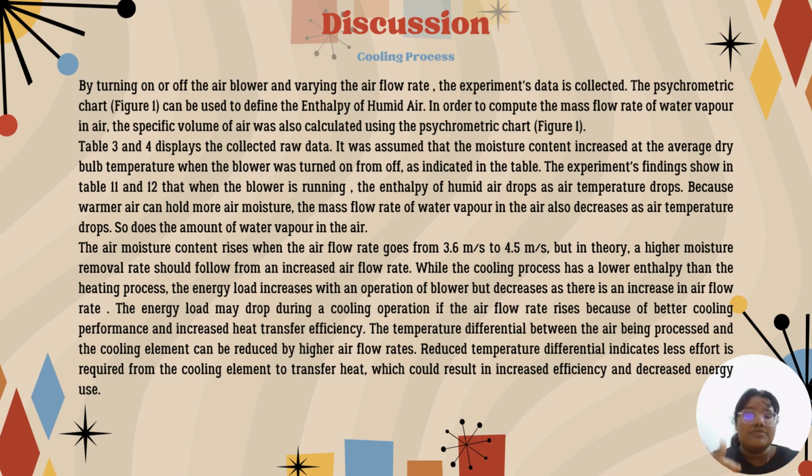The energy load increases with the operation of the blower but decreases as the airflow rate increases. The energy load may drop during a cooling operation if the air rate rises because of better cooling performance and increased heat transfer efficiency. The temperature differential between the air being processed and the cooling element can be reduced by a higher airflow rate. Reduced temperature differential indicates less effort is required from the cooling element to transfer heat, which would result in increased efficiency and decreases